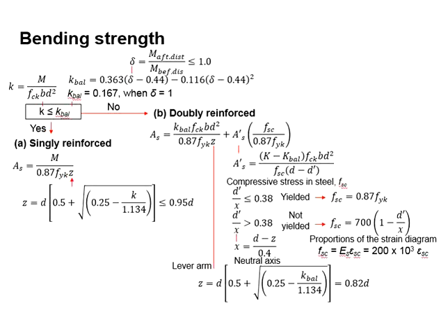In terms of the cross-sectional area relative to the loads acting onto the member, when the cross-sectional area of a member as compared to the loads acting onto it is relatively larger, then the member will be singly reinforced. And when the cross-sectional area is relatively small as compared to the loads acting onto it, then you require strengthening of the compression steel bar, and therefore a doubly reinforced member is required.